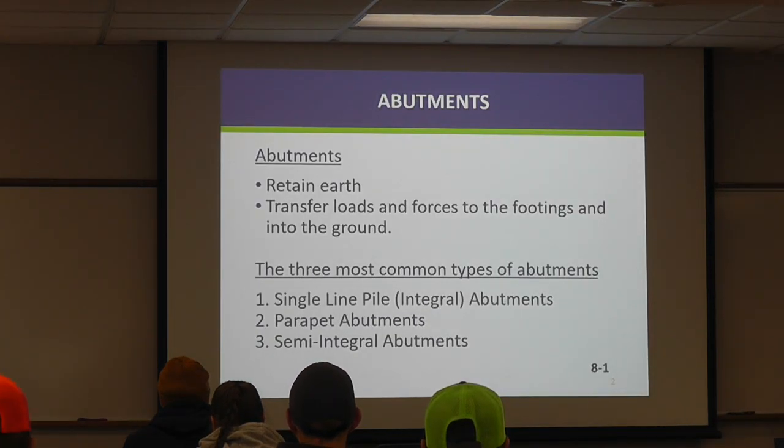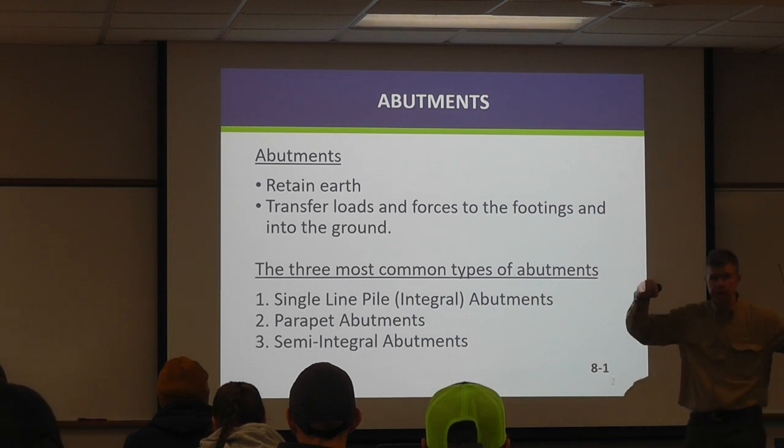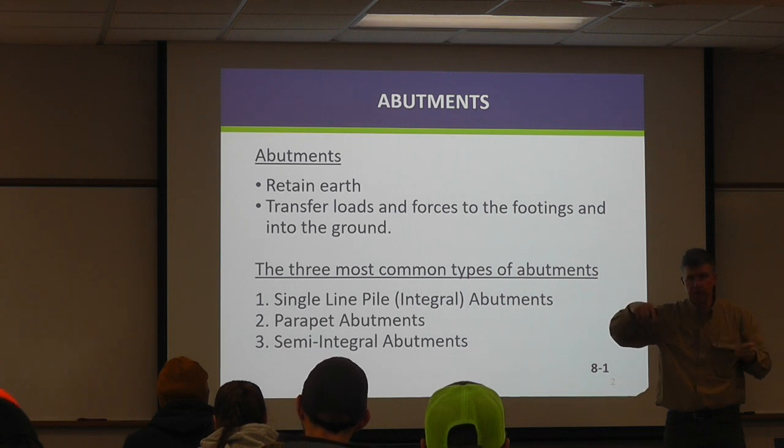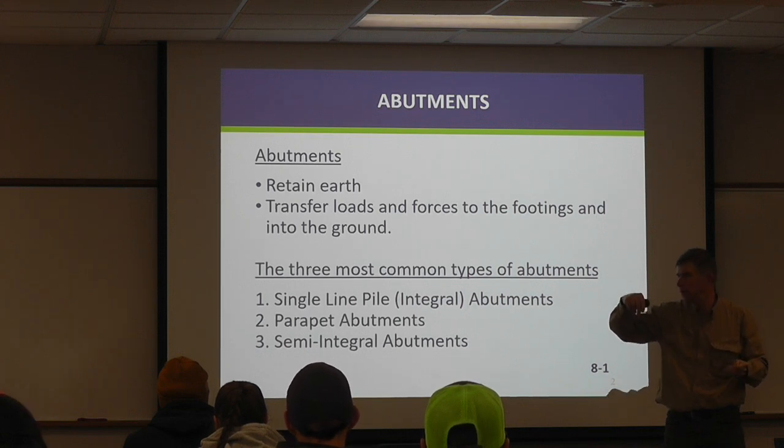So what's the purpose of abutments? It's to retain earth and also transfer loads and forces to the footings and thus into the ground. As I have mentioned, there are certainly different types of loads that abutments will have to withstand. One is the load of the beams coming across, the deck, the beams, the vehicles, everything coming across to a bearing seat or a bridge seat, and then coming down the abutment into the ground.